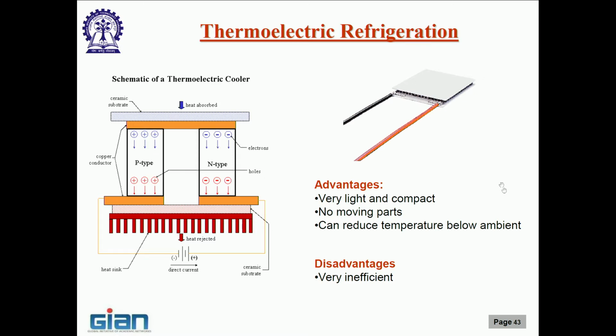Okay. Typically, when it comes to a refrigerator, instead of efficiency, we use the term COP, coefficient of performance, which is the ratio of the amount of heat that is extracted over the amount of work that you put in. In a typical household refrigerator, that COP is around 3.5 to 4 today, for the basic ones. Of course, there are more advanced, more expensive ones.